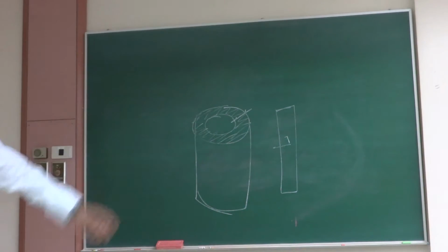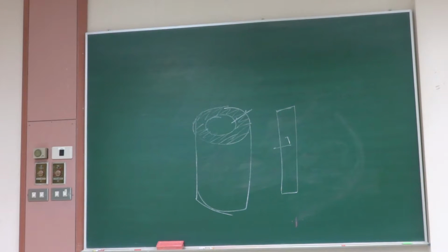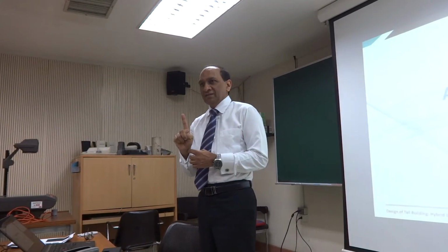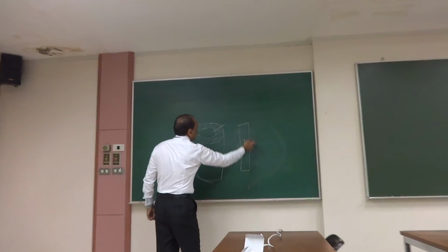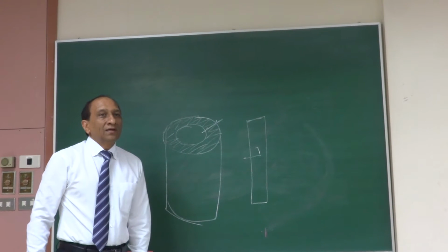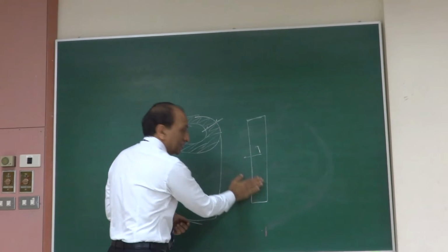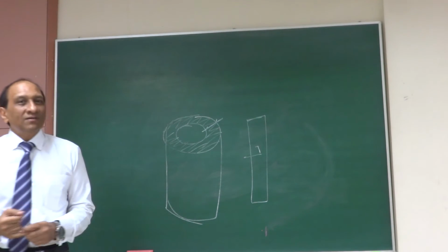This is a cylinder, thick cylinder, right? It could be anything which is like that. Okay, this one, but only with a hollow inside, okay? Just like this. So, if you look at one cross section of that, same cross section is being replicated everywhere. So it's completely symmetrical about its axis, correct? So this section, if I cut a section here, this slice is going to be exactly the same around the entire cylinder. So if I want to model this, I only need to model this element and tell somebody that this element goes around 360 degrees around an axis.